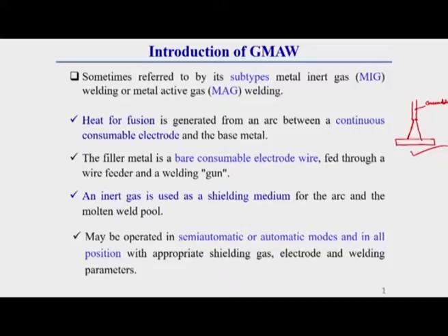In the SMAW welding process, what we have observed is that to protect the arc from atmospheric contamination, flux is used, and when the flux burns it produces some gas. So that is a somewhat different mechanism and a different type of protecting medium, but here the protecting medium for the weld pool as well as the arc is inert gas, or sometimes some active gas is also used.